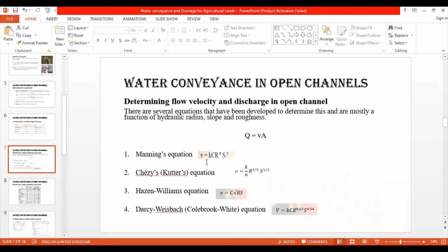Again here, you notice that the K, as I said, is due to the soil. This one will be tabulated in tables, and it will always be given for a particular soil, as well as this C, which stands for the roughness of the channel. This will also be a factor that has been determined for different materials, for clay soils, for sandy soils, and other types of soils.